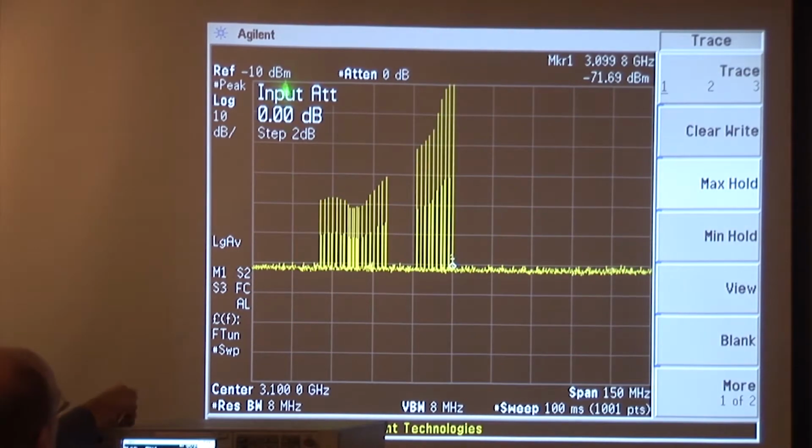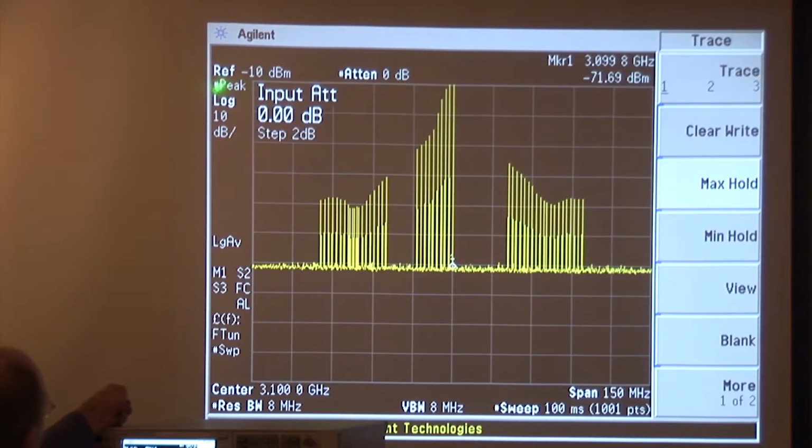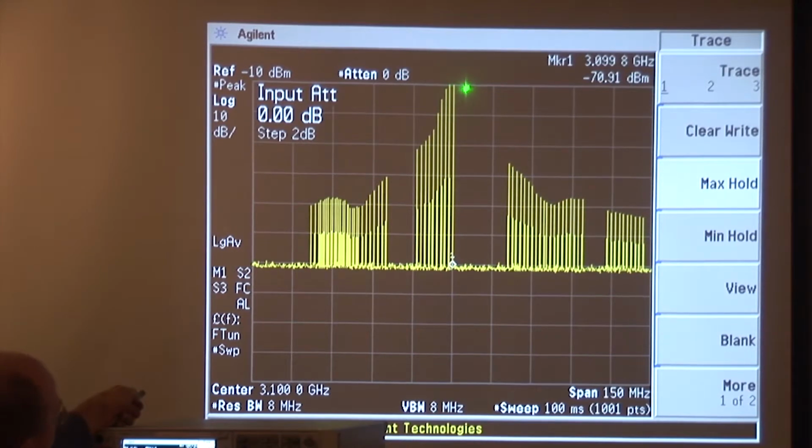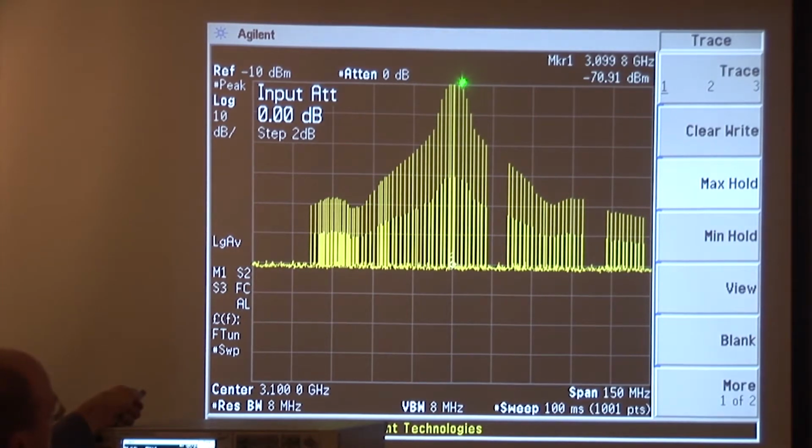And so now, because I took out the 10 dB of attenuation, the top of the screen is now at a reference level of -10. So this is going to peak out right here at the top, which means that we're almost saturating the spectrum analyzer, but not quite. If we do get saturation, we'll get a little IF overload error indicator over here, which is one of the great things about this particular little spectrum analyzer. And we're not getting that error over here, so that's good.